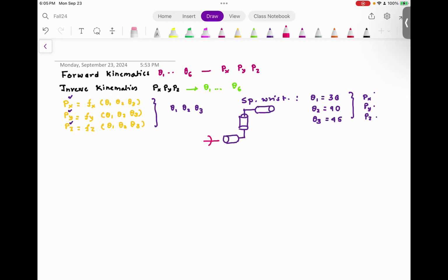This joint and this joint, if I rotate this joint by 30 degrees, and if I rotate this joint by minus 30 degrees, overall rotation is 0. Which means you cannot uniquely identify these joint angles that give you the resultant. That is the meaning of gimbal lock, which means two of these joints become parallel to each other. So the resultant cannot be resolved.